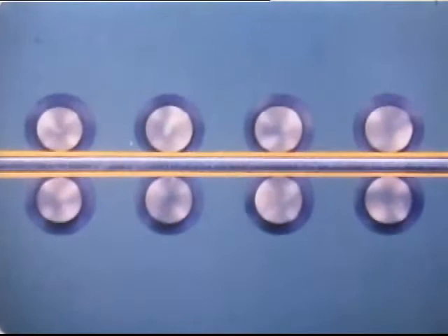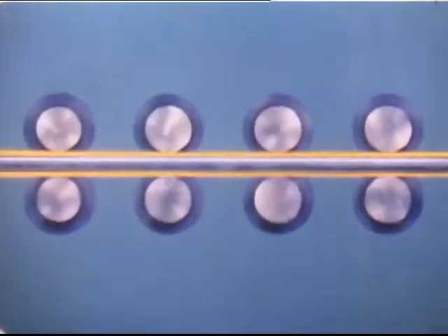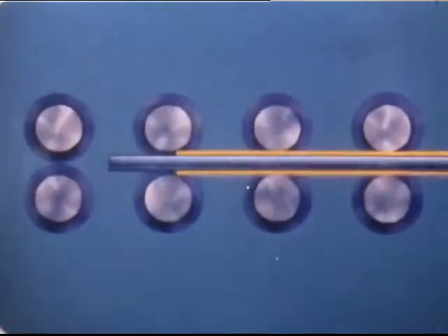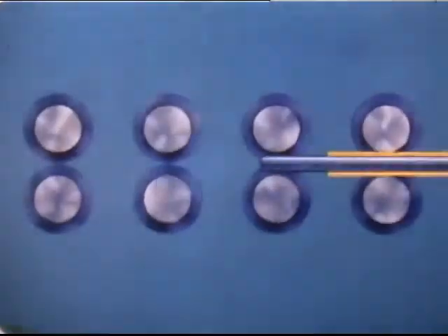The next 2 polish and perfect the surface of the shell. And the last, or 9th stand, rounds up the shell and loosens it from the mandrel. After passing through the mandrel mill, the shell and mandrel are conveyed to a mandrel bar stripper,